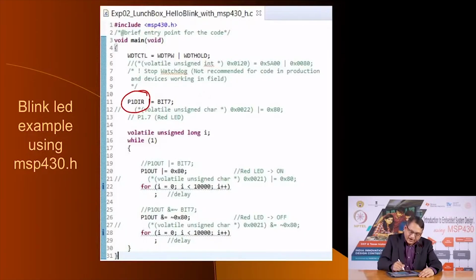These names are defined in this header file. And so we do not have to remember the addresses of those ports, we simply refer to them with these names. It is like somebody has already declared a variable whose name is this, and you can deal with these names, manipulate information in these locations.